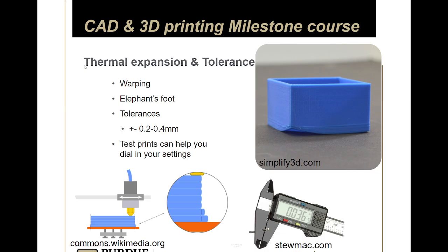There will be a little bit of excess material coming out of the nozzle, and because it's squished a little bit, it'll be forced to go out of the area of the model you originally designed for, right? So if you see in this circle image here, there's a little bit of extra material, and then there's a line where it was supposed to be, right?